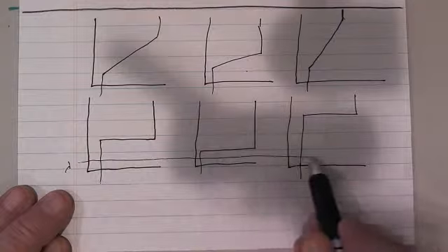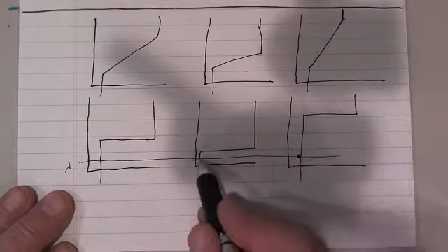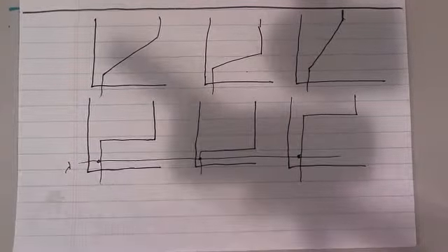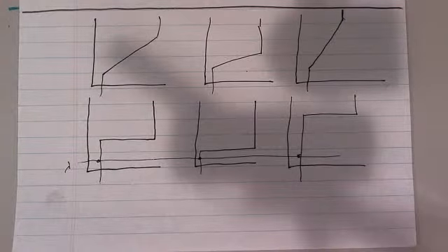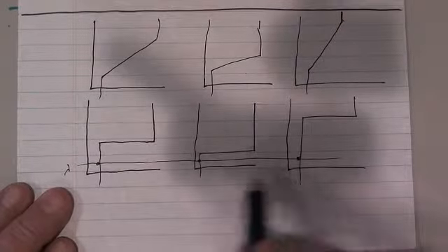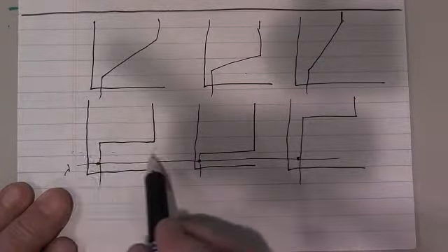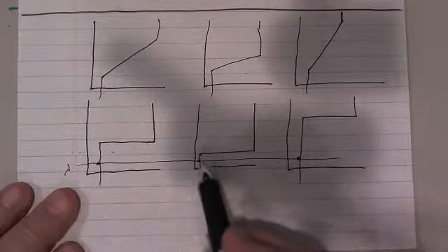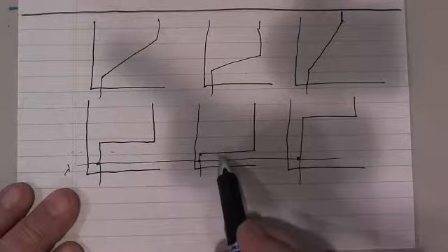Well, now if I have 3 things like this, if I put my ruler and I say, well, lambda is this real low number, then all 3 units are on their min, and we would start. I would say, well, that doesn't give me the load, so raise the value of lambda. Once you get lambda up to the lowest one here, then this one starts to come across.